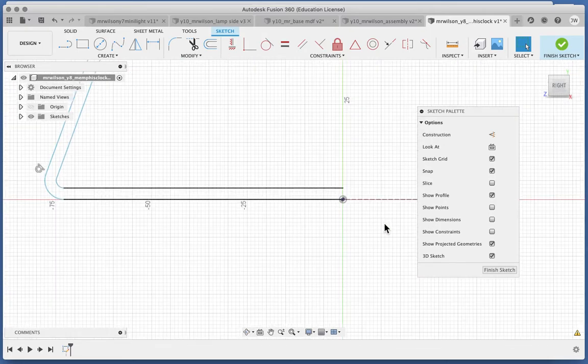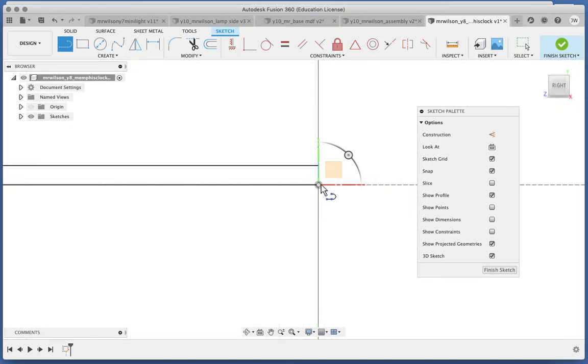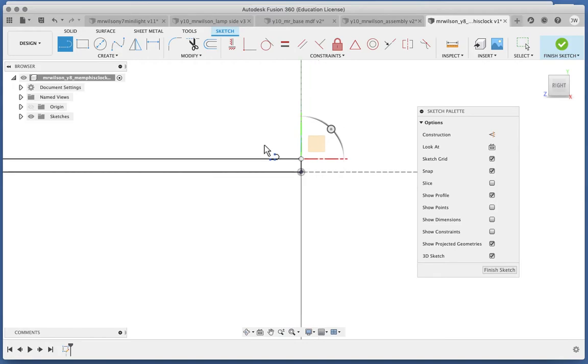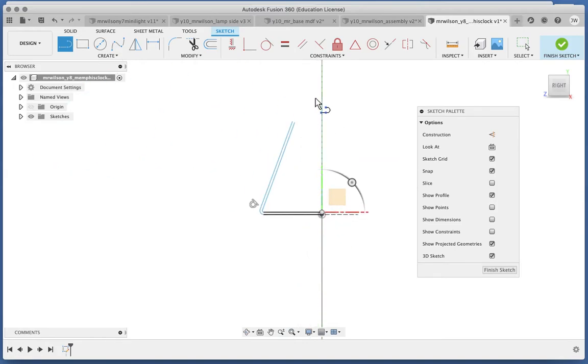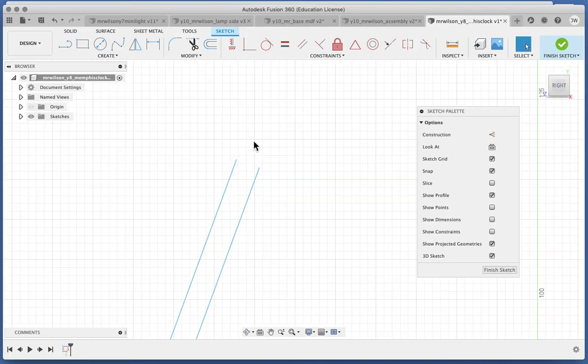That's what would happen as the acrylic stretched around a corner. Now, this is an open part of our profile, so I need to put a little line from the bottom there across to there. Okay, and it's still an open profile because it's not closed up at this point. So I'm just going to press my line tool again and click across there, and press enter.